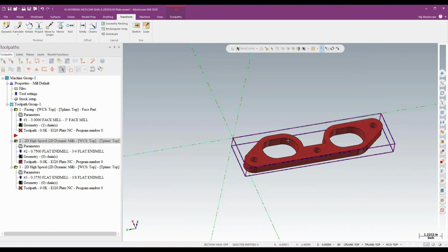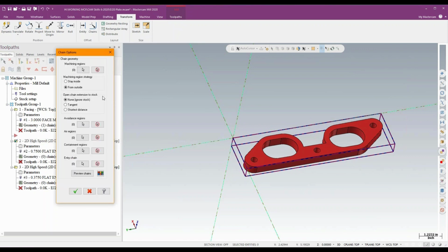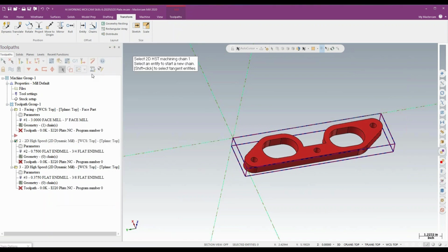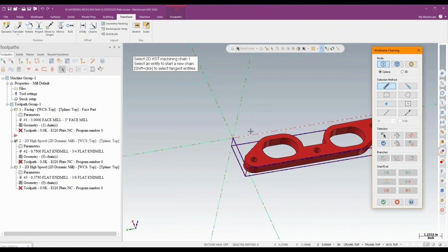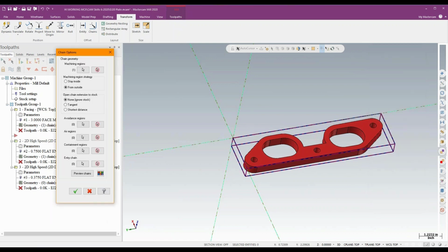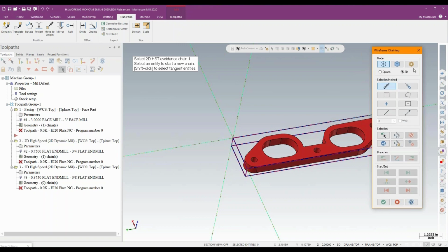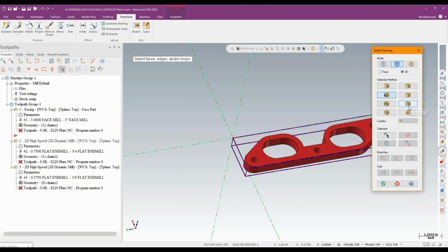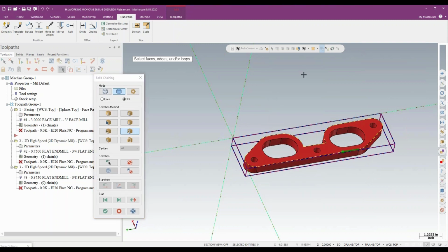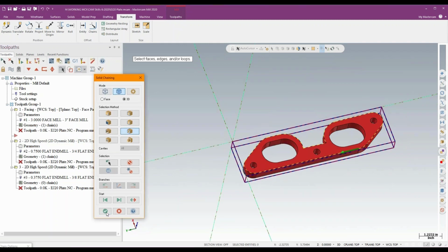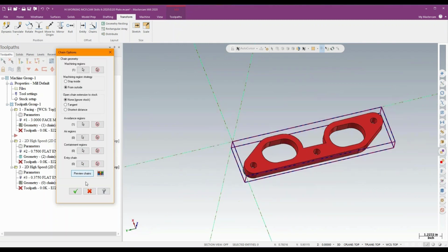My next toolpath is a 3/4 end mill. It's an outside dynamic. So I'll go ahead and just chain that really quickly. So it's an outside strategy. Again, I'll C-plane chain around that stock boundary. I'll throw a really quick avoidance using some solid chaining options. I'll use outer edges in this case to define an avoidance boundary to keep that tool off there. There we go.